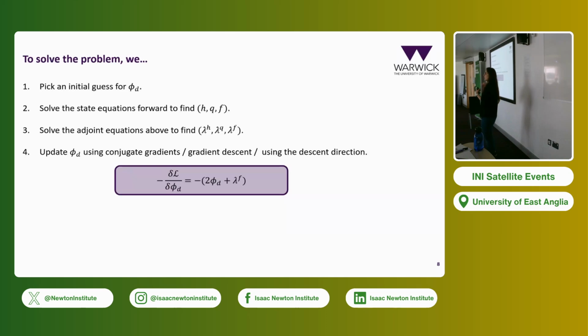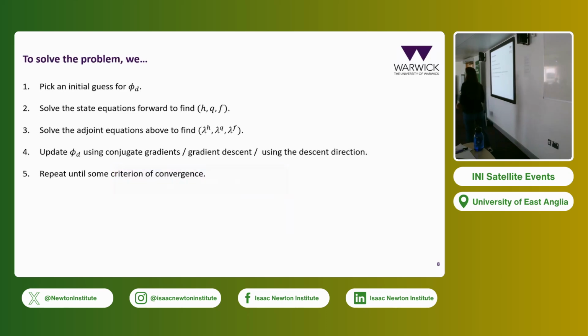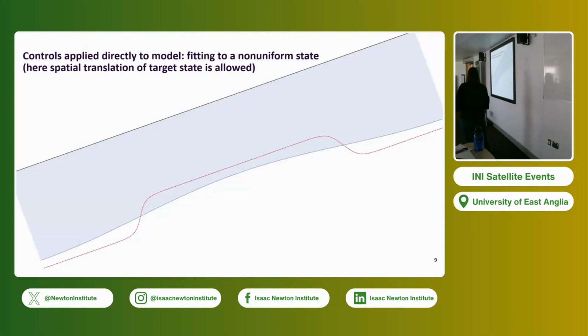So usually you know that you go in the direction of the gradient, but do I just add the gradient? Do I add 0.1? Do I add 0.5? And normally if you're solving a normal optimization problem with a function that's not too complicated, you just evaluate your function at like 10 points. And then you pick the better one or the best one. But in this case, you would have to solve your PDE in like 10 points or 1,000 points, whatever. So there's clever things you can do to minimize the number of PDE solves to do this well. And then you repeat this until you converge. And what converge means, you can decide. But yeah, you look at your cost functional and how it varies, and when it's not varying too much, you assume it converged. So how does it work in practice?